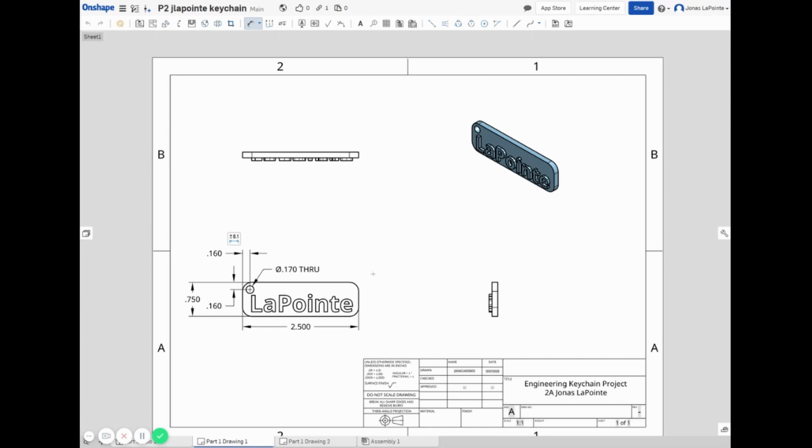If you have a curved corner and they're all symmetrical, you can do one of them, and we're going to click on the curve. And anytime we do rounded objects, like we did with this through hole and this curve, we're going to move diagonally to label it. And if you look, I can pull this up, and this is lining up so that our through hole dimension is on the same horizon line as our radius. And I'll click that. What this is saying is there's a radius of a 2-inch circle. So if I put a 2-inch circle in here, that would be the radius of this arc we have here. All right, our front view is looking pretty nice.